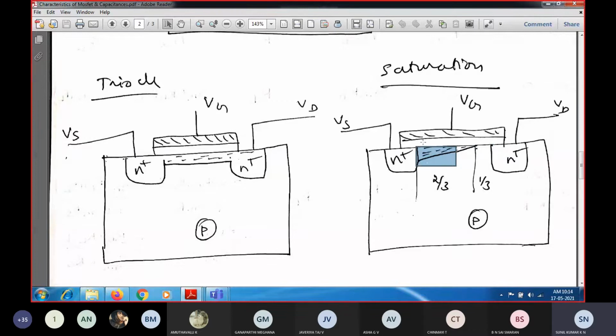capacitance effect is because of the gate to source. Since the source is connected to ground, it is not going to be affected, and only the gate voltage appears. Because of this, the inversion takes place across the source, because the source terminal is connected to ground, whereas across the drain end, even though the drain voltage applied is positive, you can see some of the channel getting pinched off across the drain end, and the contribution of CGD is one third of the COX.